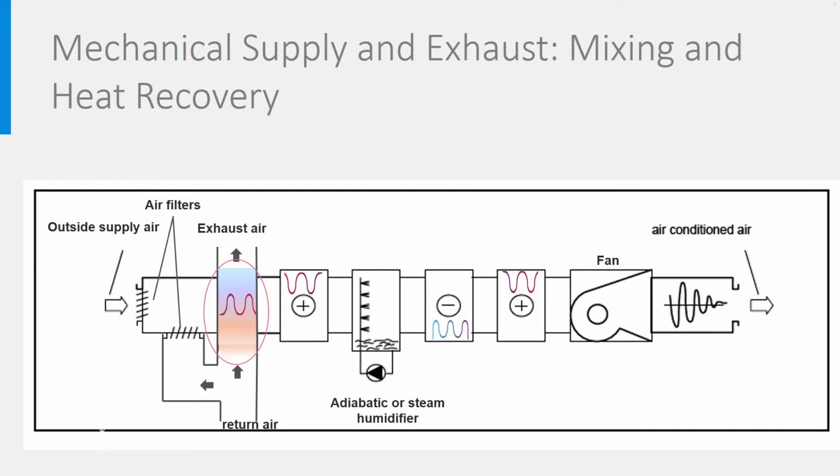In some systems, recirculation is applied, meaning that a part of the return air is mixed with the clean outdoor supply air. This is a cheap way of preheating or pre-cooling the supply air, but is only responsible when the flow rate of return air being mixed is very small in comparison with the flow rate of the outside air. Otherwise, the concentration of indoor pollutants could increase a lot.